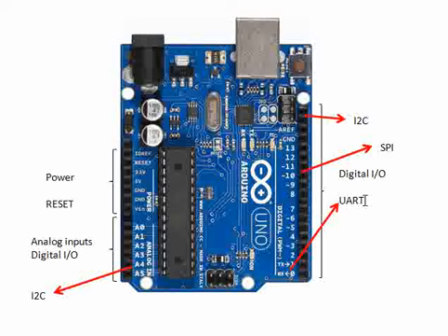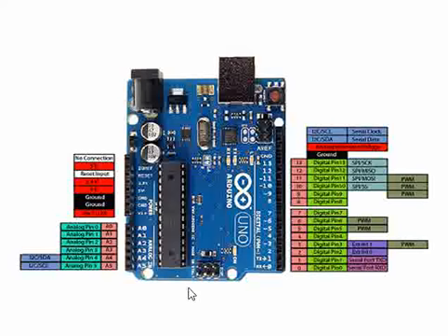And then you have UART here, you can see the TX and RX, and then you have SPI in the middle, and then I2C. So while this gives a basic glimpse of the pins that are connected, this gives us a deep insight into the alternate functions of each and every pin. You can see these are power pins, and then these are analog pins, and you can see the SDA and SCL, the I2C pins here.